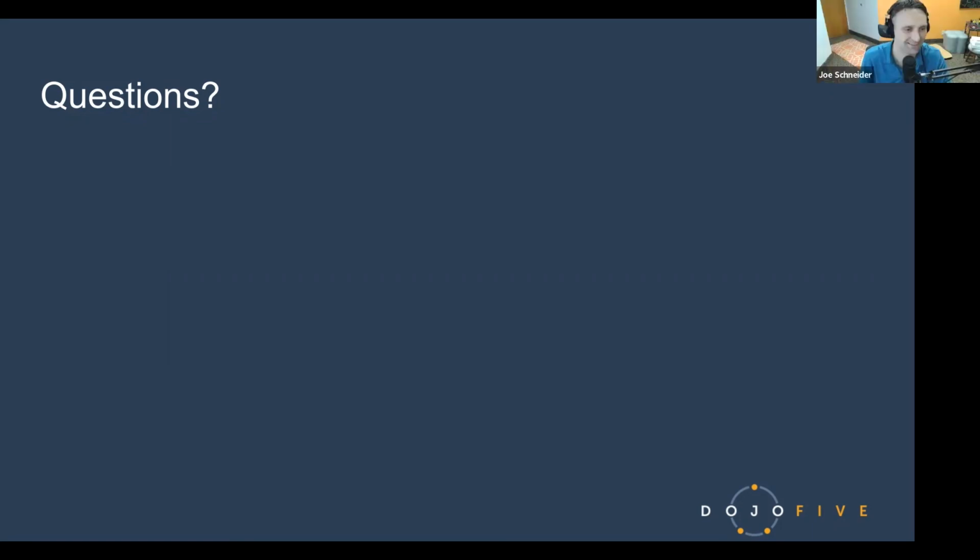Yeah, nice. Let's see, a couple more have popped up. Concerns about leaving a larger attack surface for the nefarious types. We kind of addressed that already a little bit, but that's why you want to do a release build. And it really depends on your threat model, right? Are we worried about the CLI if we've left JTAG on there and enabled?